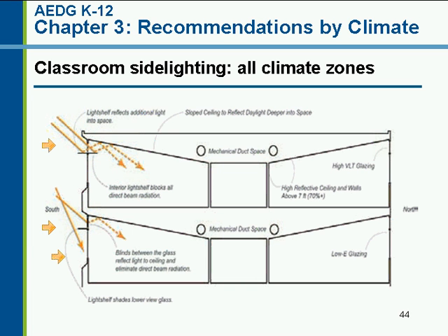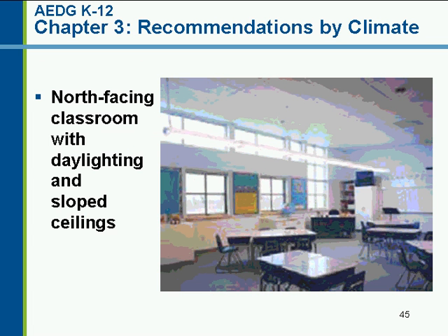When you look at the north side of this, on the right side of the building, you don't need any of those light shelves, you don't need the overhangs, because there's no sun to block on that side. So as you're doing your building, be thoughtful about how you treat different facades.